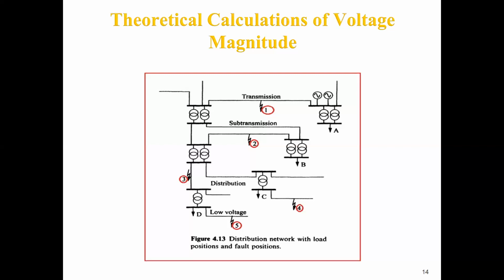As there are no generators connected at a lower voltage, there is nothing to keep up the voltage. Once this sag is available to all the customers connected here, there are no other generators to boost up the voltage.